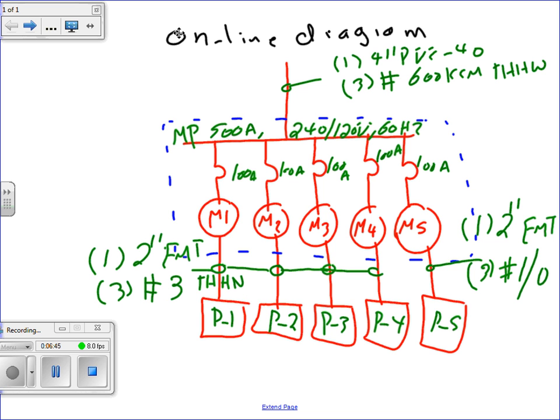Now, Ashley came and she said, Chad, I would like to use an NM cable instead of EMT inside, or USE cable. No problem. I suggest to use conduits: inside EMT, outside PVC conduits. Any questions guys about the one-line diagram, before I move into the security riser?